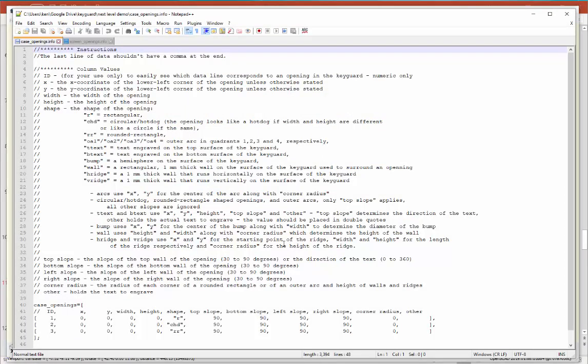What we're going to do first is we're going to make that major cut for the case itself that surrounds the home button. And remember, we were going to create a rounded rectangle. So I'm just going to go ahead and overwrite this part here with a double R, rounded rectangle.